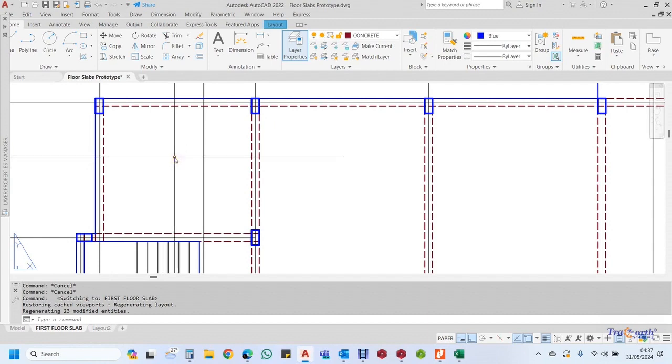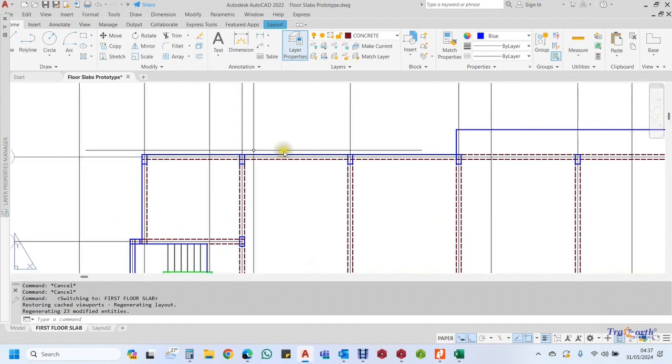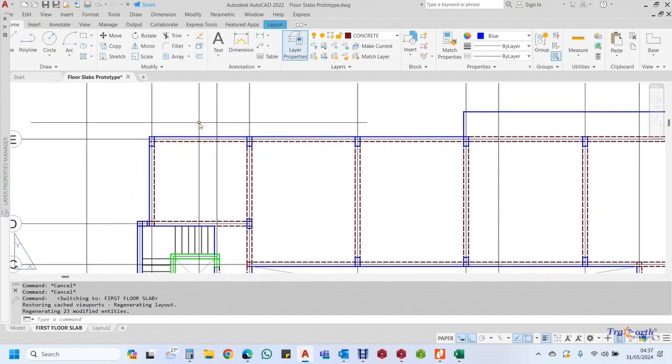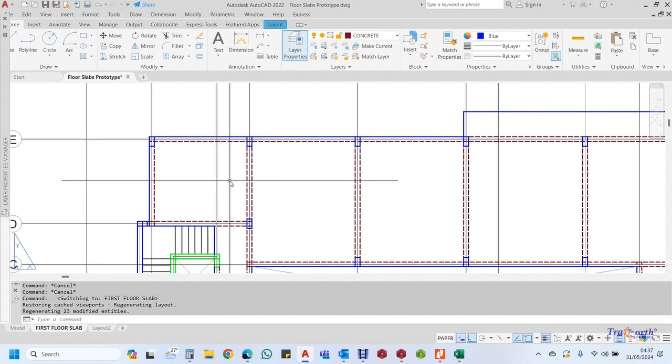That is one scenario. The other scenario is when the longer side of the slab divided by the shorter side is more than 2. If the coefficient or the factor, our Ly over Ls factor, is more than 2, that means it can be designed as a one-way slab.